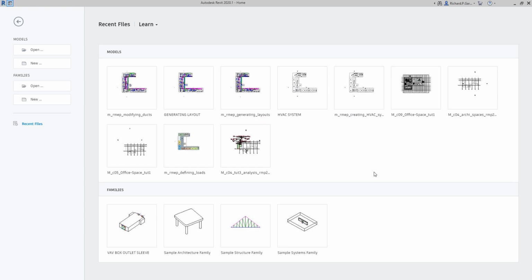In this video, I'm going to teach you how to create a VAV box. Specifically, we are going to create a dual duct VAV box. For those who are just starting in HVAC design, VAV stands for Variable Air Volume box. It is a part of an air conditioning system and it is located inside the ductwork. It is designed to control the airflow to a specific area called a zone.